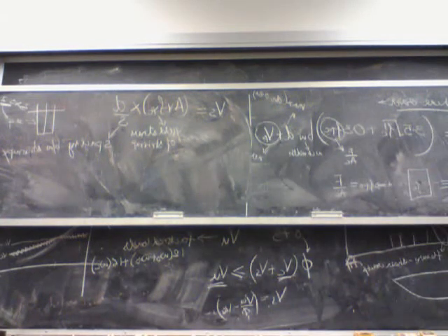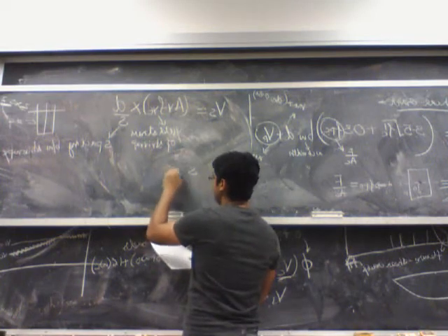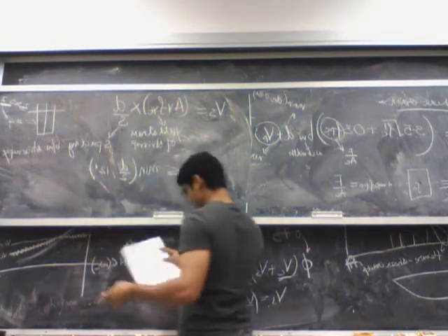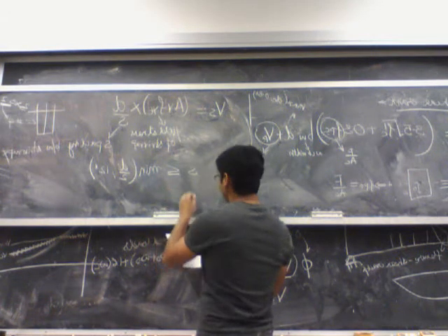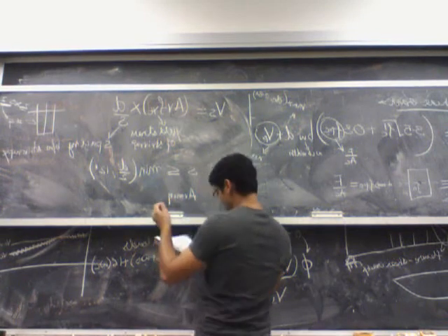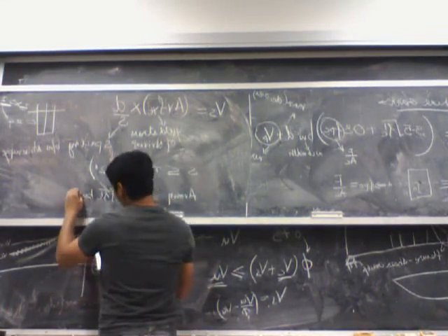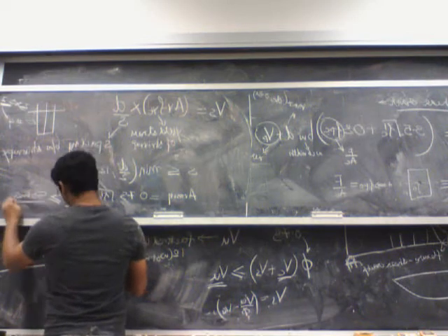Then there are some other limitations on all these. There is a limitation on the spacing which says s has to be less than or equal to the minimum of d over 2 or 12 inches. And there is a formula for Av min also. This is 0.75 square root f'c b_w s over fyt. This has to be greater than b_w s over fyt.